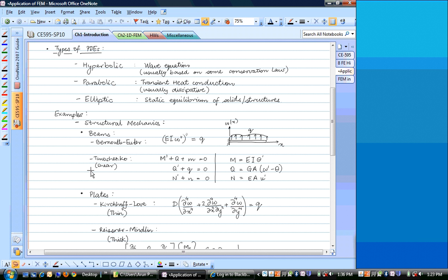And the other type of theory that we have is a Timoshenko beam theory. So did you guys cover this last semester, maybe in 570? Towards the end? Okay. So in Timoshenko beam theory, the important thing to remember is that that is a thick beam, so shear deformations are not negligible. In the Bernoulli-Euler beam, the deformations are always in a pure bending state.